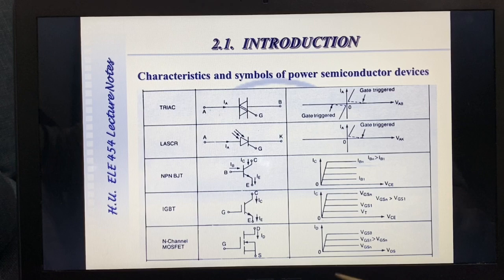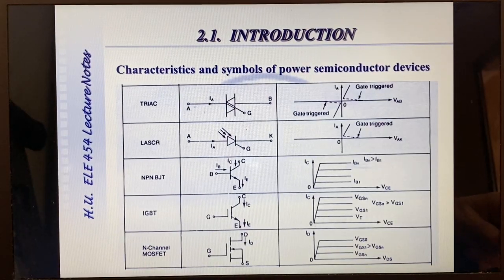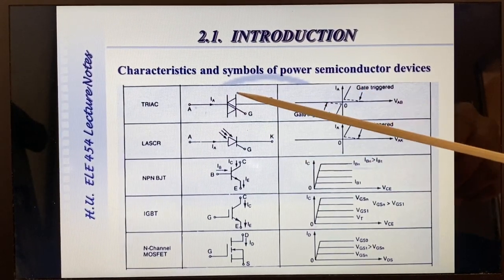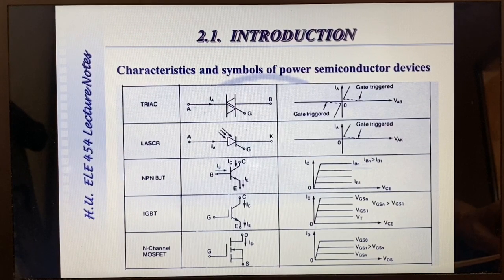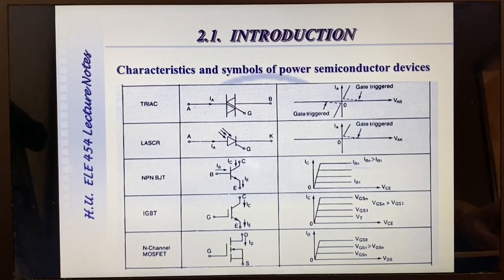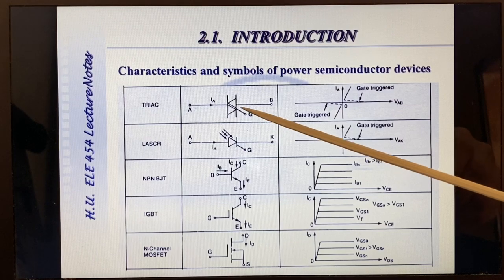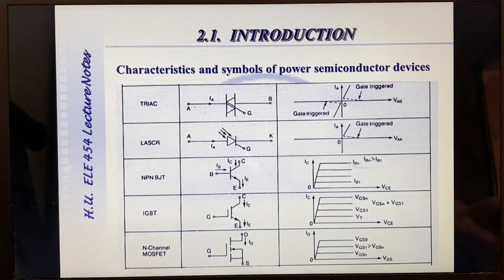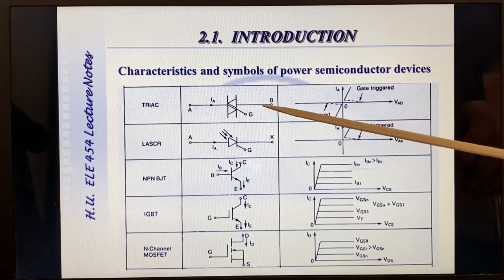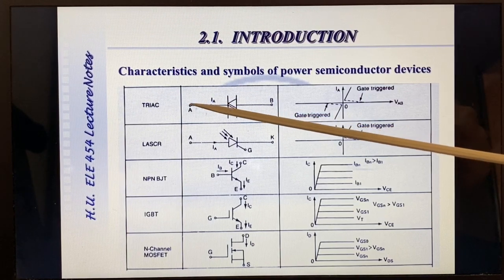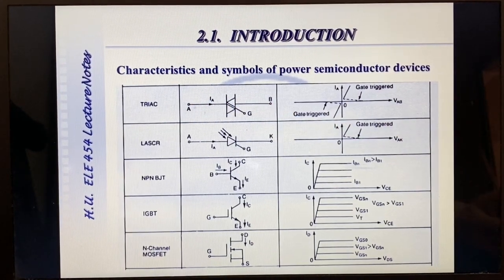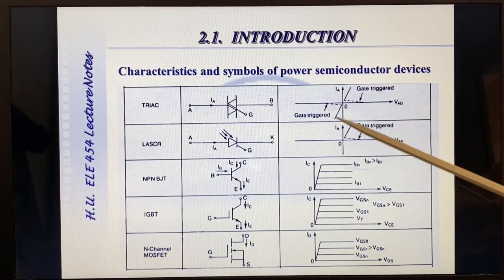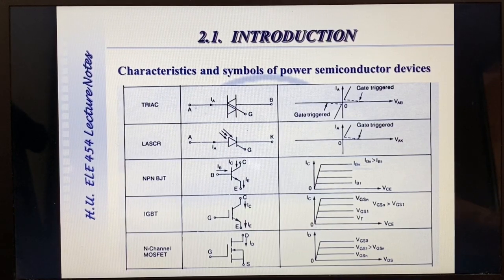So this is a very special type of power semiconductor, only used in very, very high power applications. Let us continue with triac power semiconductor, which can be considered as two back-to-back connected thyristors. Again, the triac is put into conduction by applying a gate current with respect to one of the terminals, and it can be triggered into conduction in both directions. IA can be positive or negative, as it is seen from the characteristics of IV plane in the first and third quadrants.